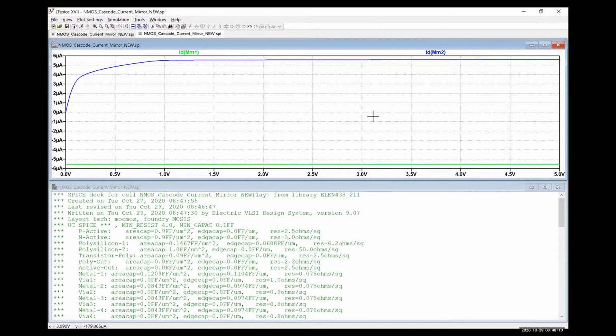So I'm getting around 5.5 microamps, which is not really what this thing is designed for. The reason I'm only getting 5.5 microamps is because I'm not actually pushing that PMOS transistor really far into saturation. The threshold voltage for the PMOS transistor is going to be 0.9 volts below VDD, and I'm only 1.1 volts beyond that, where my VDsat for these is about 250 millivolts.